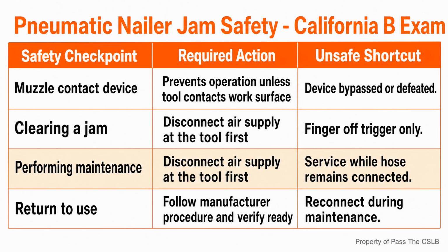When I make a final shear panel walk, I use 4 words to keep the inspection organized: support, schedule, seating, and safety. Support means every required panel edge has framing or solid blocking behind it, and the fasteners actually hit that backing. Schedule means edge and field nailing are identified separately and match the approved structural information. Seating means the nails maintain the required panel edge distance, land in the framing, and are not driven through the panel face. Safety means the nailer has the required contact safeguard and is disconnected at the tool before jam clearing or maintenance. I would perform that walk before the work is concealed.